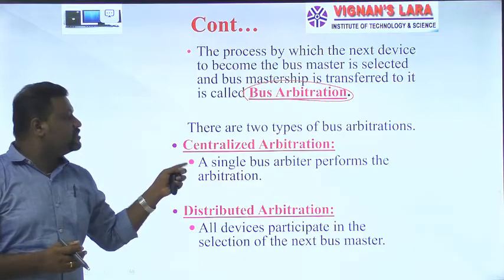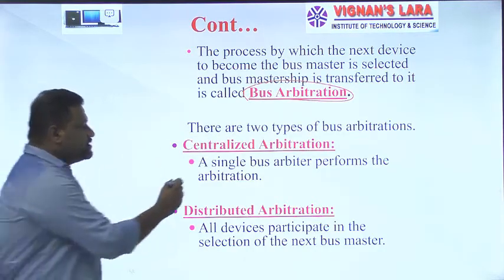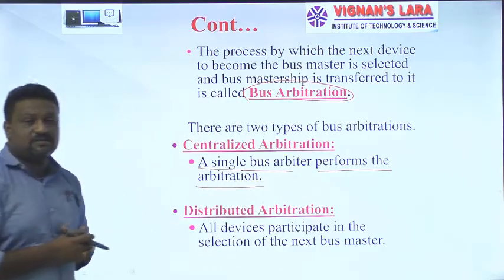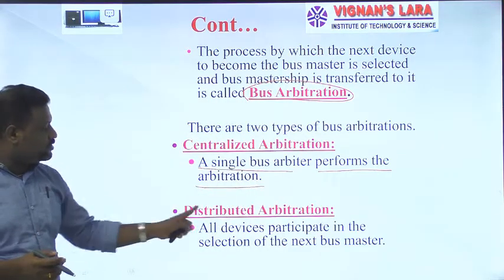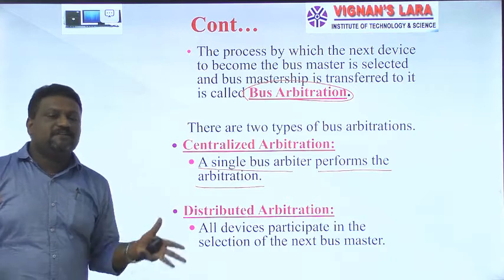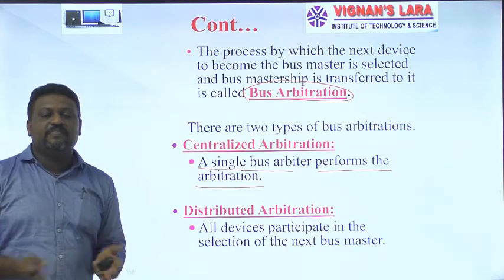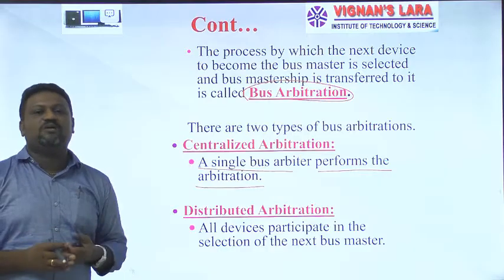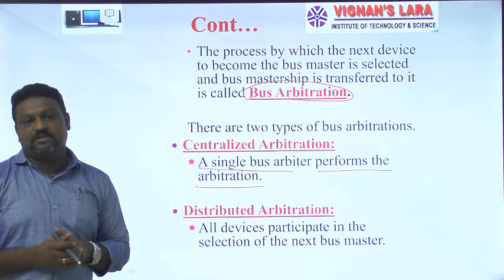I repeat, in centralized arbitration, a single bus arbiter performs this arbitration process. But coming to the distributed case, all the devices which are present in the system are involved in this bus arbitration process. That's why it is called distributed bus arbitration.